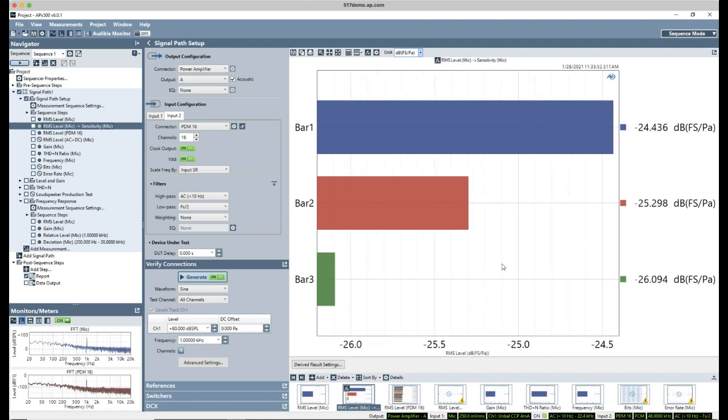We'll take advantage of this sort of, I'll say, natural cancellation of the source speaker when we measure frequency response. But this is quite handy because, frankly, there is no such thing as a measurement speaker. This is one of the interesting things about the world of audio measurement, there are absolutely measurement microphones. And a measurement microphone is a microphone like any other microphone, but the key property is that it has a flat frequency response.